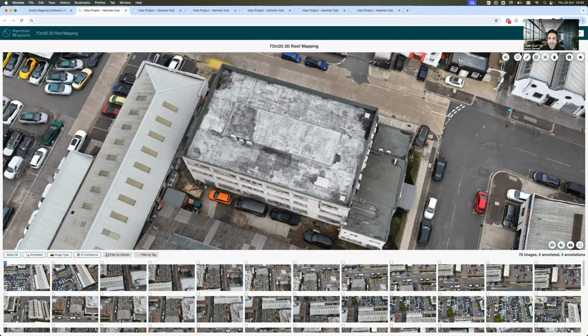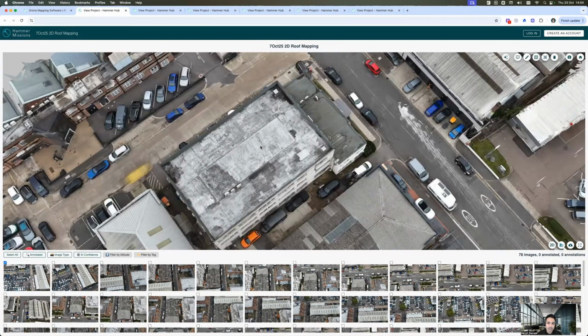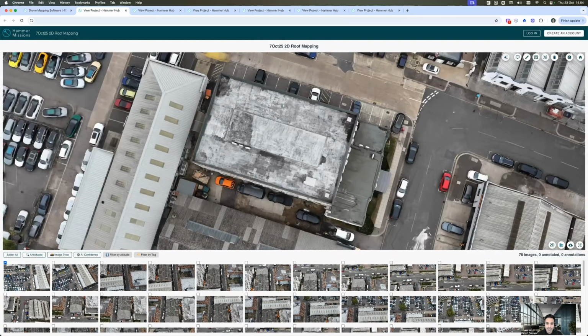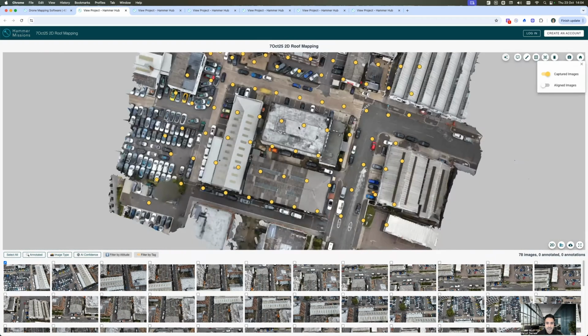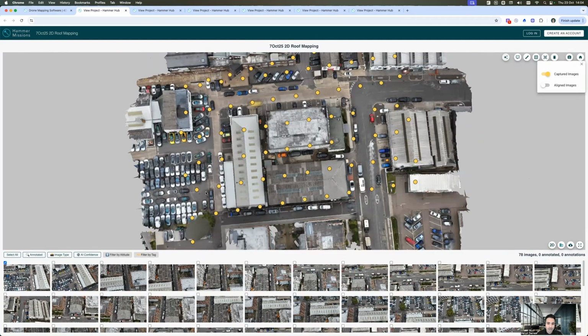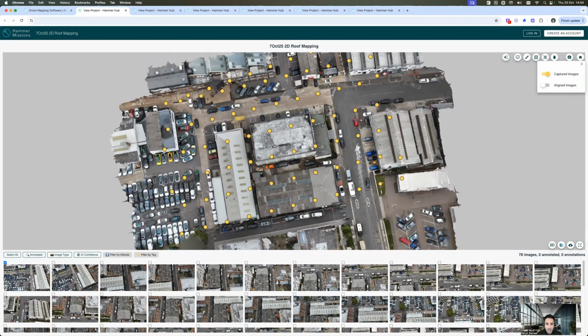The very first flight plan that was used to capture the data is a 2D flight plan. So basically flying a single grid, where, let me bring up the image map, you're essentially flying left to right or right to left in a lawnmower pattern on the top of the building to capture it. And this could be a building or any other type of structure. But basically you're flying left to right in a lawnmower pattern.